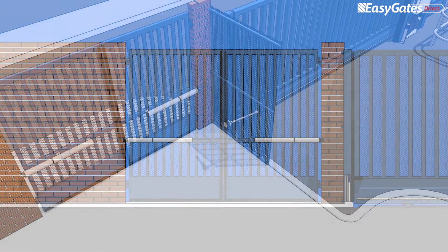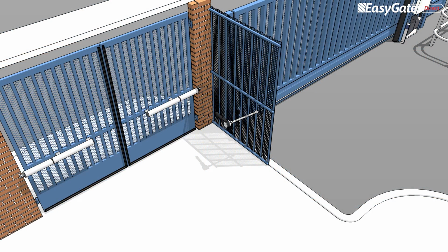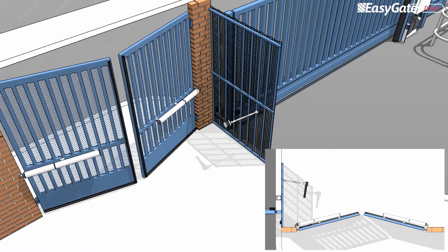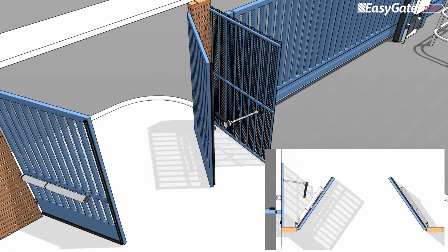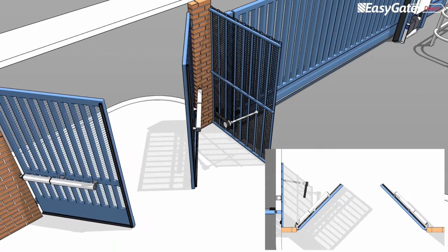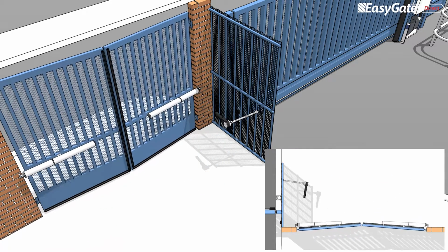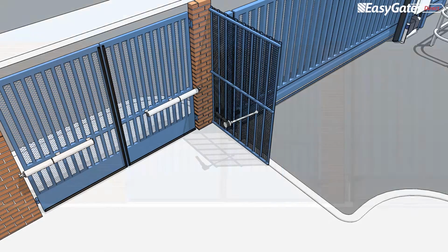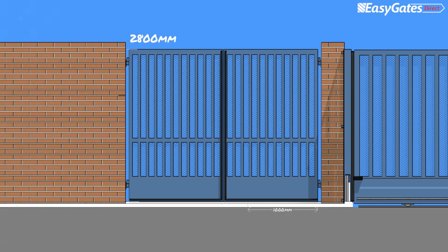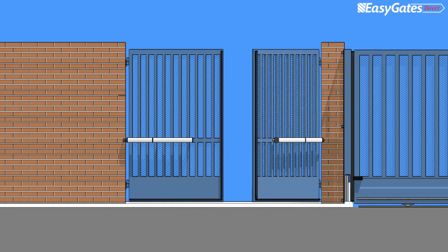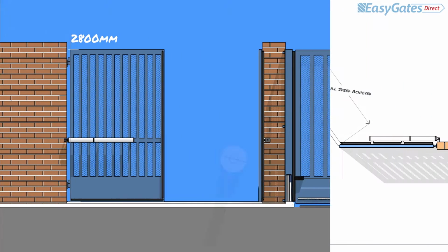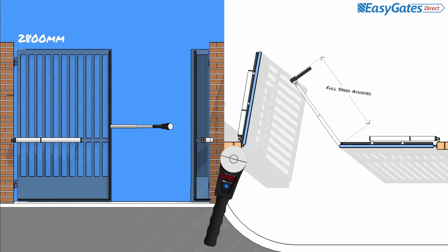Now we can see a typical swing gate opening hazard where the flat leaf surface is open within 500 mm of a wall or a fixed object. Swing and folding gate open crush hazards are measured at the most outstanding feature up to 2 meters above the ground, or in the absence of protrusions on either surface, 1 meter out from the hinge, 1 meter up from the ground. If motor slowdown settings have been used to achieve these pass results, an impact test should be carried out at the point the leaf achieves full speed, and at the center measurement height of the gate.